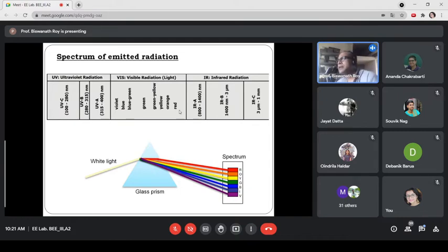The cost of the filament lamp is minimum 15 rupees, but the cost of the 40-watt fluorescent tube lamp is much higher, and it has a number of components, the lamp, the driver, etc. But we get more light from the fluorescent tube lamp of the same wattage, 40 watt, which means the conversion efficiency from electrical power to light is more in the fluorescent lamp compared to the tungsten filament lamp.